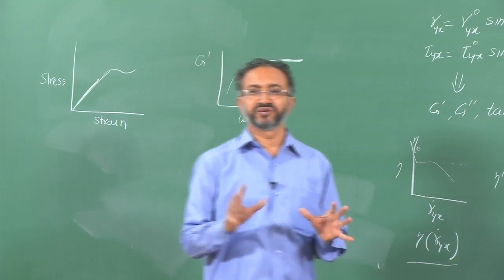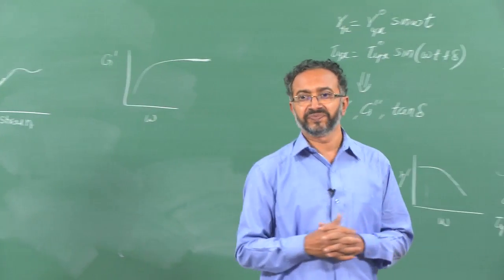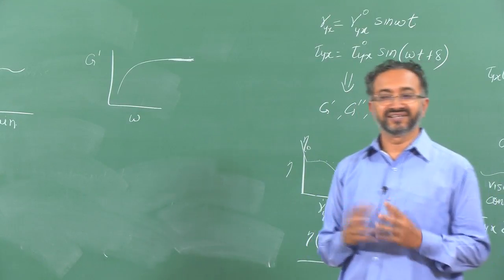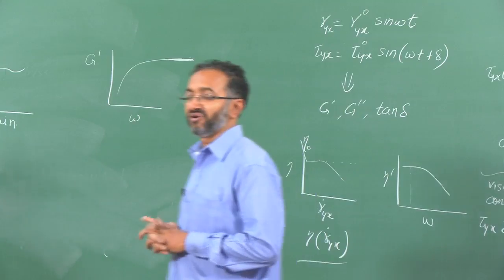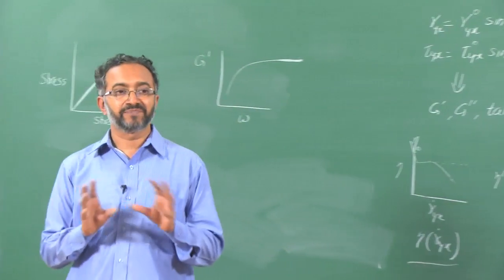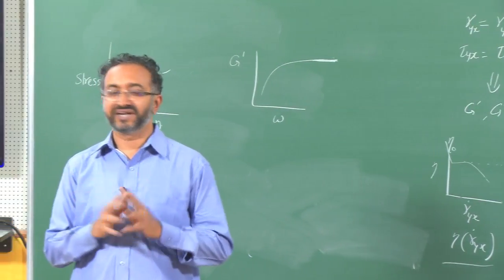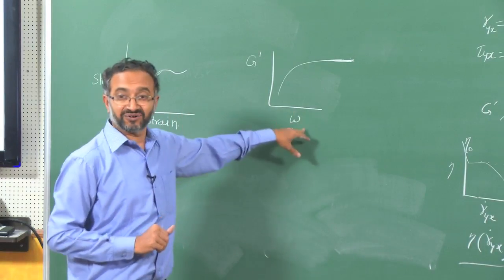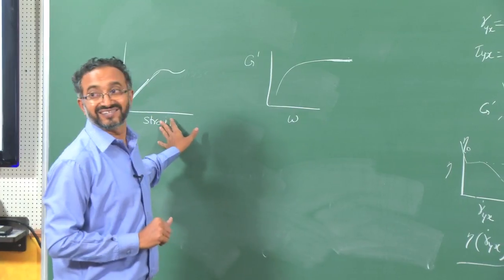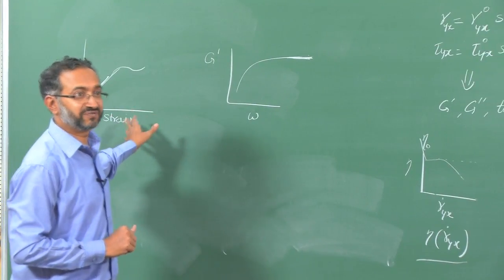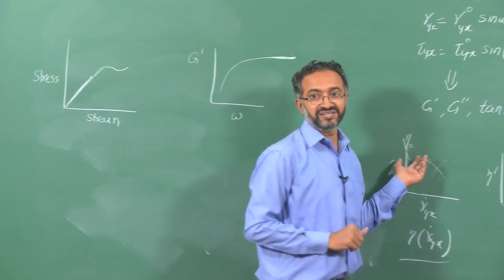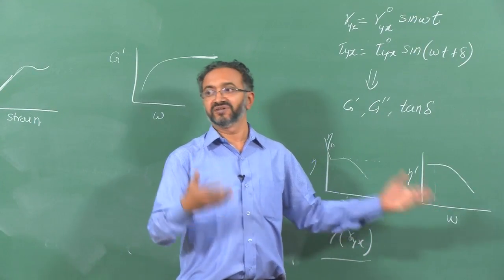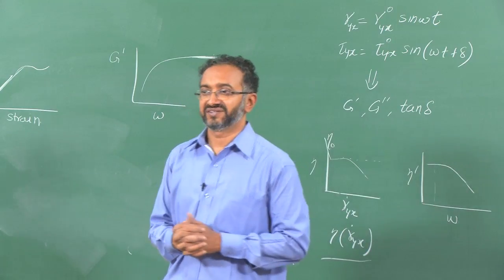So, what are your initial thoughts? Is it useful to relate like this, is it useful to think like that, or should we be careful in comparing properties of this kind? In the end we are measuring modulus, the elastic contribution, Young's modulus of elasticity, and viscosity, dynamic viscosity, which is the viscous contribution to the viscoelastic material stress.